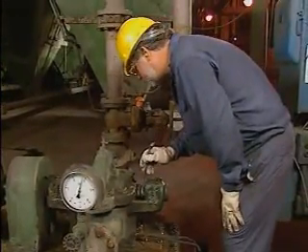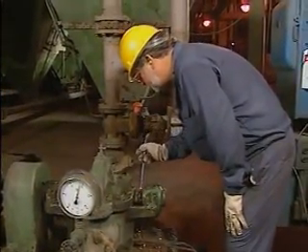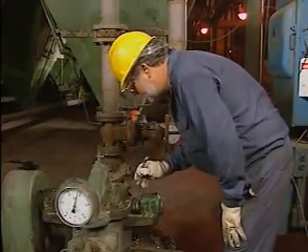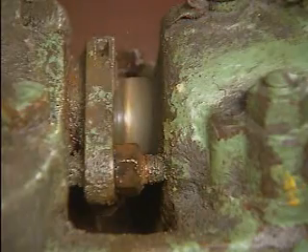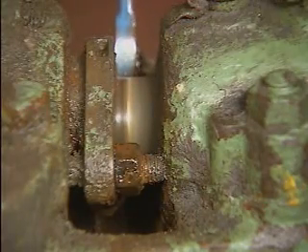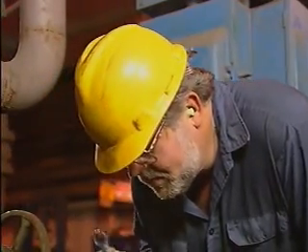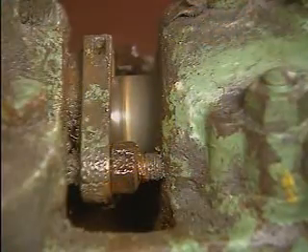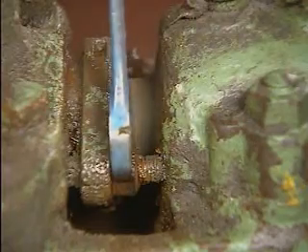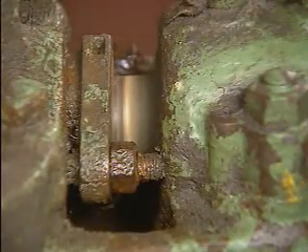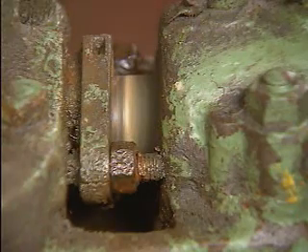After several minutes, the mechanic slowly tightens the nuts on the gland follower, which compresses the packing to obtain the desired leak-off rate. To avoid damaging the packing, the mechanic tightens the nuts in even increments and waits a few minutes after each adjustment to allow the packing to cool off. This technique helps to prevent the new packing from overheating when the pump is first started. Once the desired leak-off rate is achieved, the installation is complete.